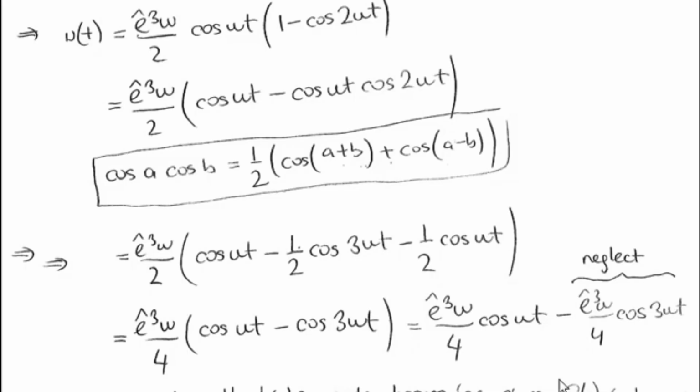Remember that our system is actually linear and it has low pass characteristics. So therefore these high frequency components are actually going to pass through that linear system, which will attenuate these terms. So therefore here, in describing function analysis, we are going to neglect all of these higher order terms, and we are actually going to be assuming that u of t is only composed of this term which has the same frequency as the input here.